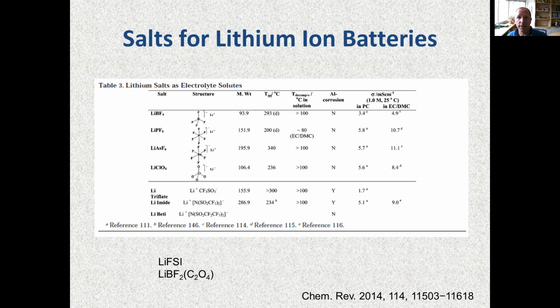So as I mentioned at the beginning, lithium tetrafluoroborate, LiBF4, is a very good salt. LiPF6 is the most widely utilized salt. Lithium hexafluoroarsenate is another one, which was one of the first salts utilized for lithium-ion batteries. And lithium perchlorate is also another one that's received a lot of attention.